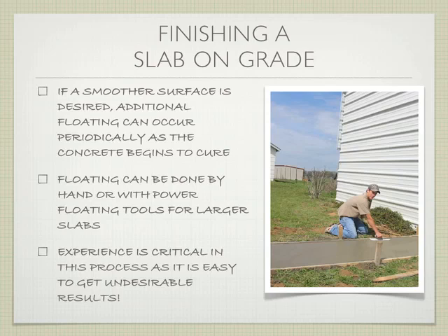It's entirely dependent on the humidity, the temperature, the speed the concrete's set to cure, what kind of accelerants or decelerants are in it, does it have fly ash in it, what's the mixture? All these variables come into play, and so a good concrete worker is going to know when the right moment is to do the next floating. They just kind of intuitively know, they've seen it enough to know what to do.